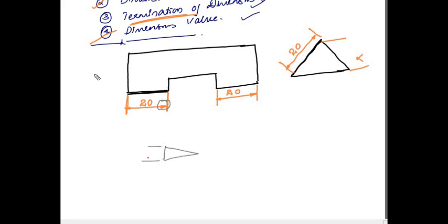if the height or the width is 1 unit, then the length is usually 3 units. It's not that every time we draw we will measure 1 and 3, 1 and 3, 1 and 3. It comes by practice, but this is the standard that we have to follow, and this should be a filled arrowhead. Filled arrowhead.